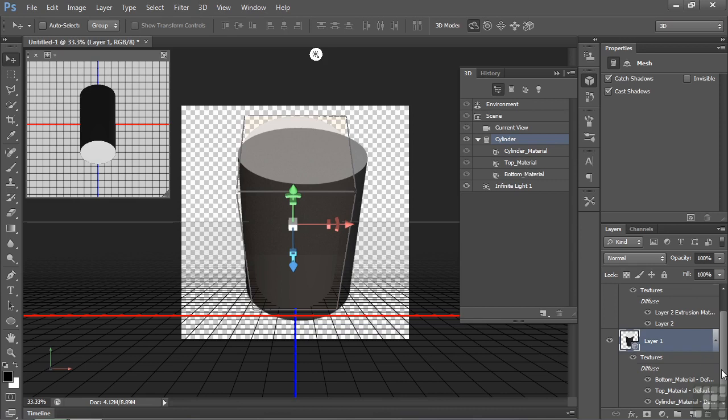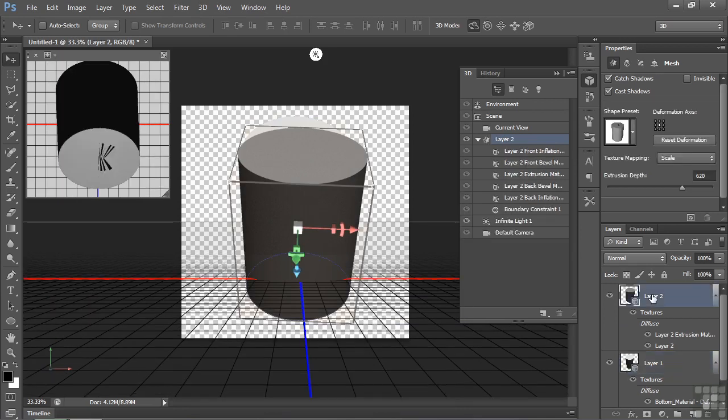If I go up to the one above that and click on this one here, this is the one made with the extrusion. It has more properties. It has those 3 plus some presets and some other things down here. Plus it has these other guys up here, deform and cap, along with the coordinates. Many more options when you have an extrusion. Another big difference is that you cannot create an internal constraint with a mesh preset. Let me show you how that works.